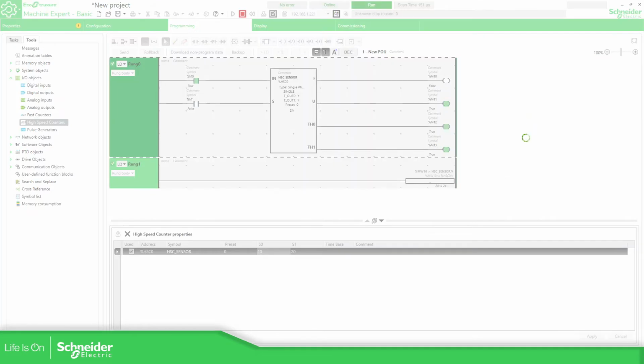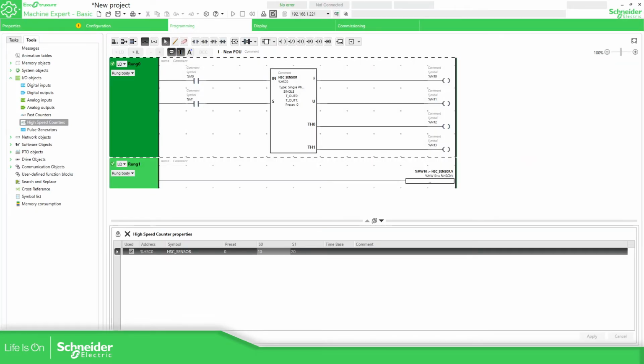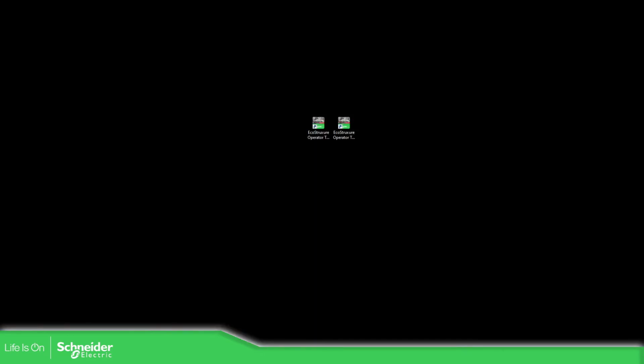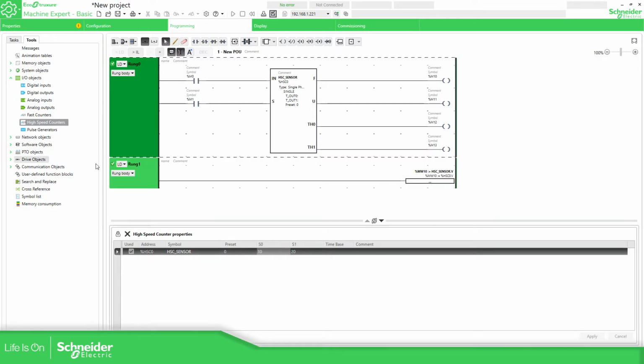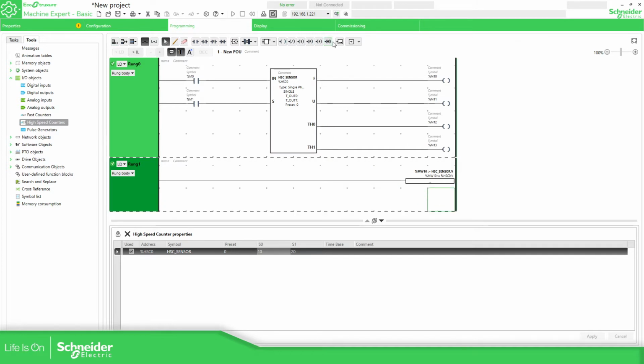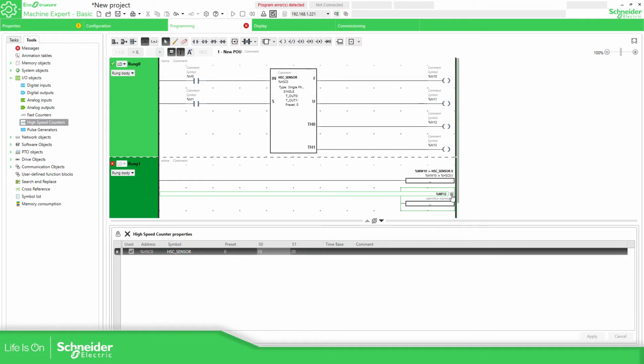So let's disconnect from here. Just go down. Okay, so I'm going to disconnect from here, and now let's add the calculation over here. So what we need to do is to convert this. So I'm going to use %MF12 := INT_TO_REAL(%NW10). So I'm going to convert the actual value into real.